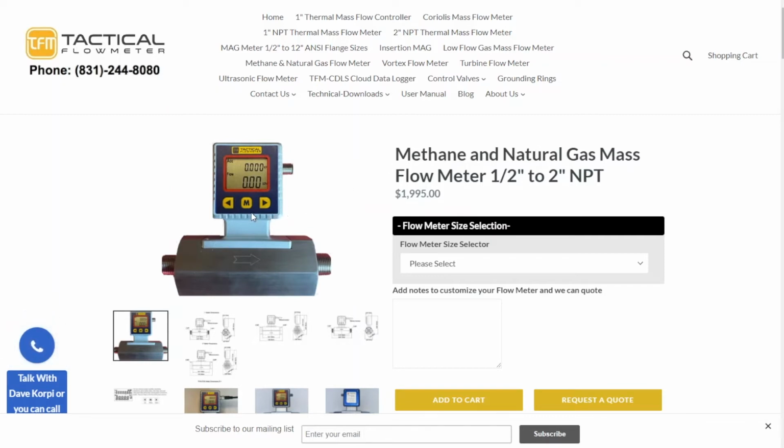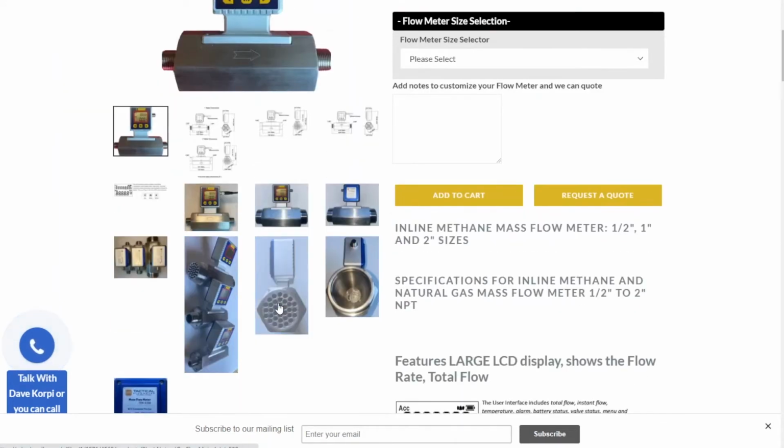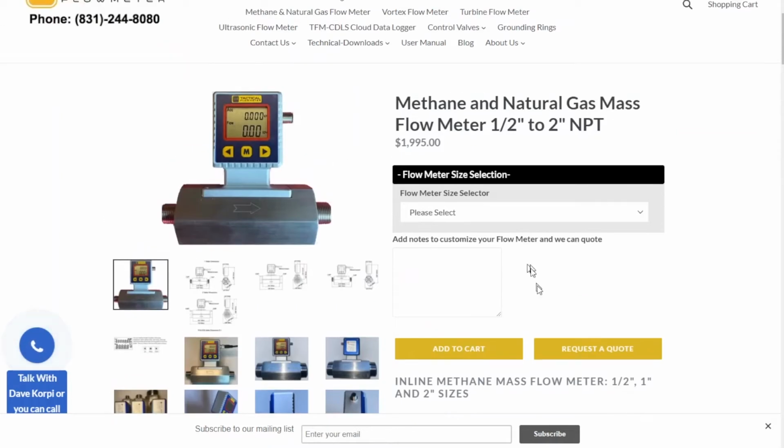The benefit of this flow meter over conventional thermal mass flow meters is that it's a time of flight machine. It's in the time domain, different than Q equals HA delta T or a constant temperature thermal anemometer such as those I made at Sierra. The improvement is you don't need to worry about the composition of the gas when you're making the gas flow through it. We have a number of sizes, but the communication protocol will become clear.